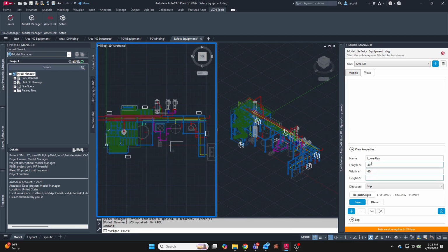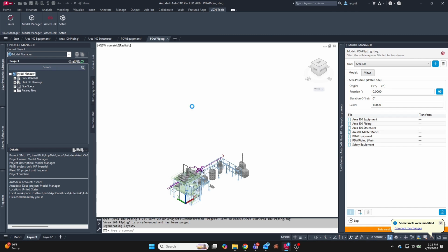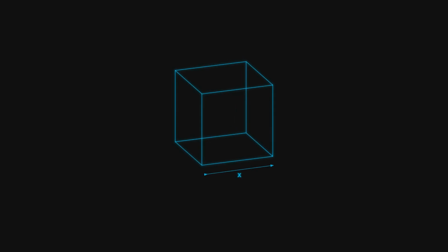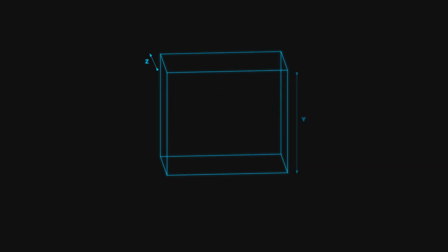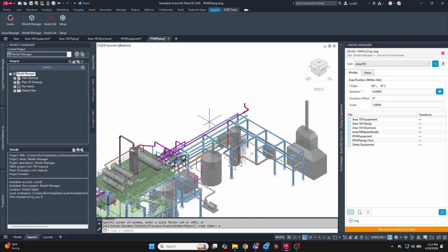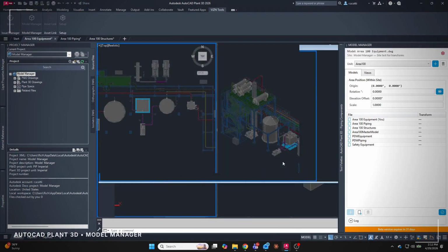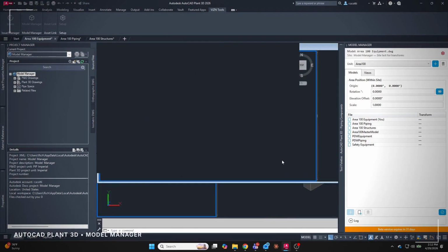They define reusable 3D volumes and can be inserted directly into paperspace as scaled viewports. To create a view, the user selects the origin of a 3D rectangular area or box. Then the size and direction of the view can be added or edited anytime. The preview button draws the 3D box in all viewports. This view can be applied in any viewport, including front and back clips.